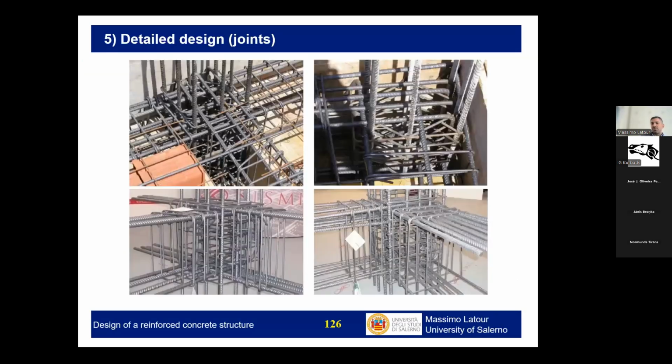These are some examples of layout of bars within a joint. Let's remind that we have to put these stirrups into the joint, which, if you're not designing in a seismic area, is maybe not always required, or not required at all.